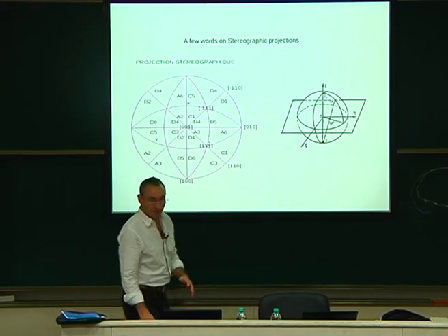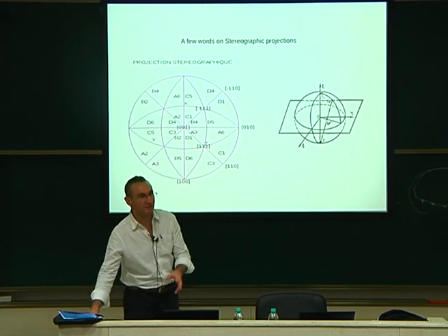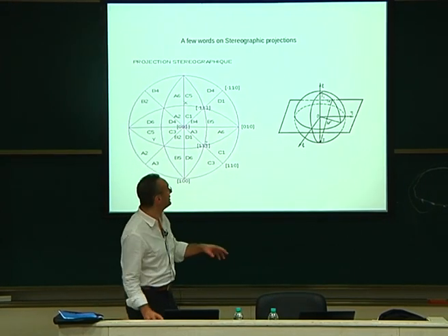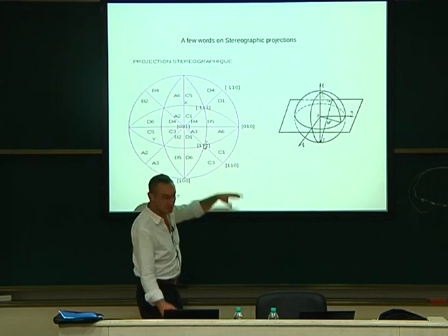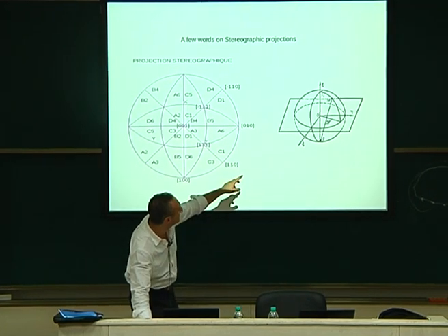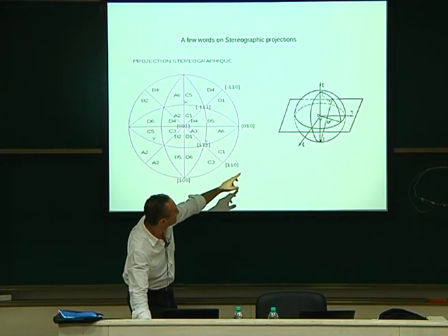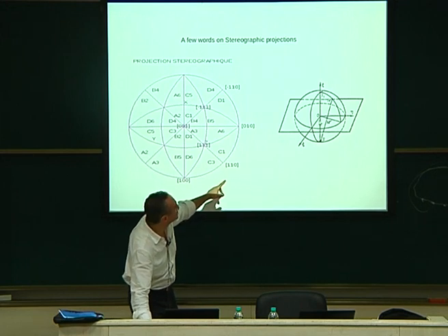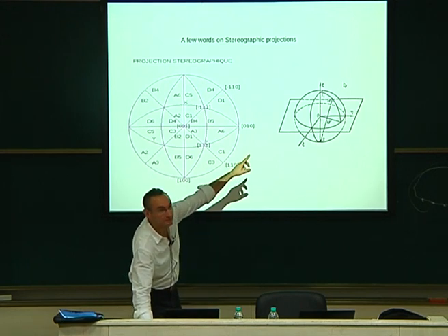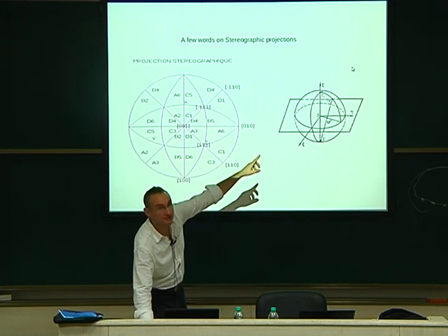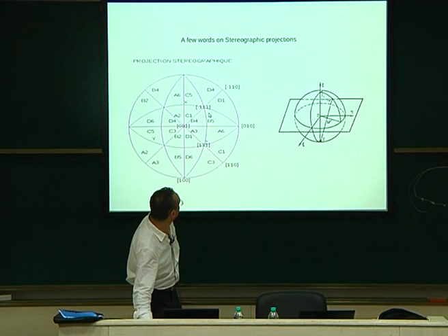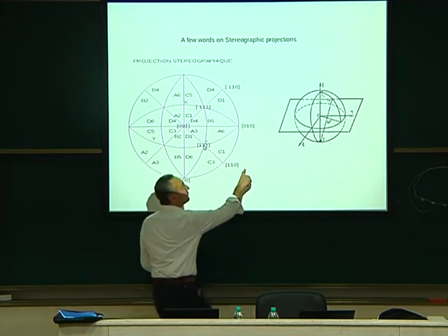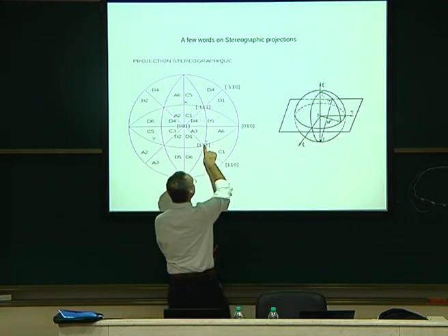Okay, so what I want to do now is ask Professor Sundararaman to explain why such lines appear here. This 1, 1, 1 corresponds to an orientation. If I had drawn my cube, I would have put a cubic lattice here, for example, and just assume that you have the 1, 1, 1 direction. The 1, 1, 1 direction gives a line that pierces the sphere at a given point. If I put back the point, it will fall here. So you have your 1, 1, 1 point here, projected there, and it gives this point here.